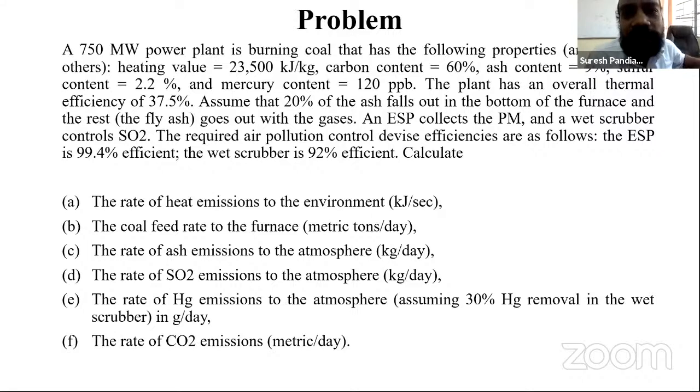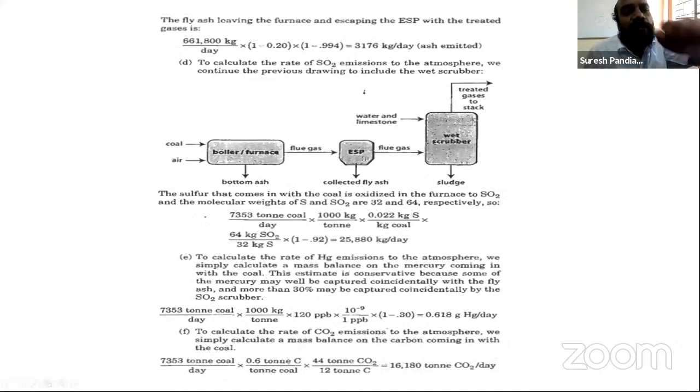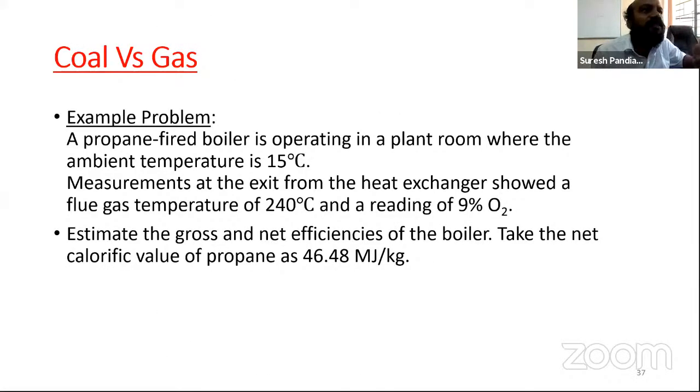This is for the power plant, right? How to calculate the carbon emission for a power plant. The key point is the 37.5% thermal efficiency. From that we find the fuel energy supplied with the coal combustion, then the mass of the coal combusted, then the carbon emission. One can talk about it, which is in the order of 1 ton of carbon dioxide per megawatt of electricity produced. Finally the readings are converted into that.